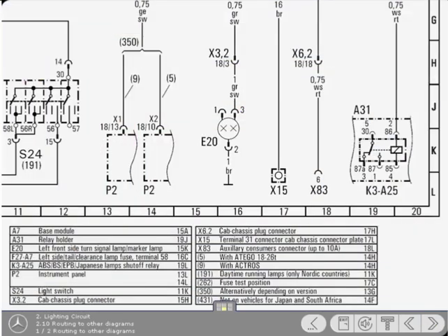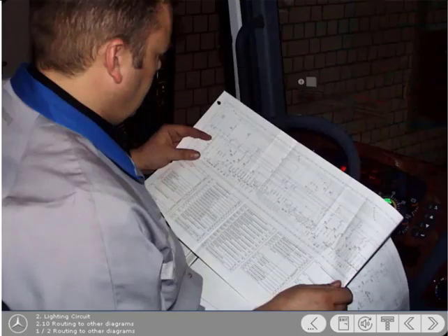You may have noticed that the diagram shows only the bulb monitor control unit cable connecting to the instrument cluster. It's a similar situation with other components on the diagram. For example, the left front indicator marker lamp and the ABS relay. The reason that the remainder of the circuits is not shown is to simplify the diagram and avoid unnecessary lines, which make it confusing for the user.